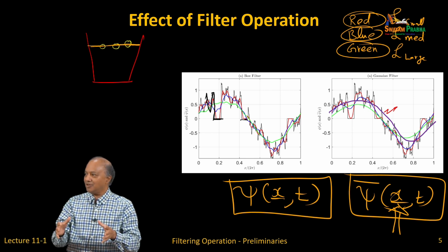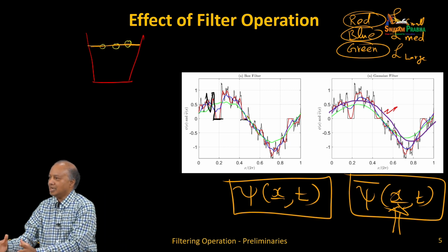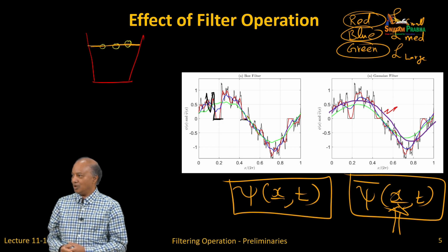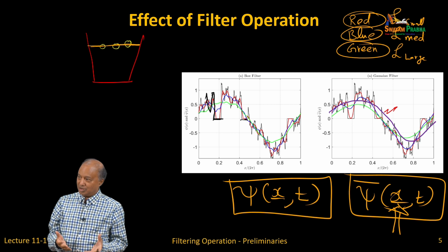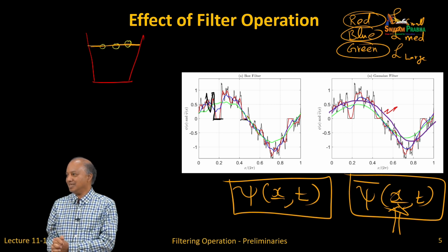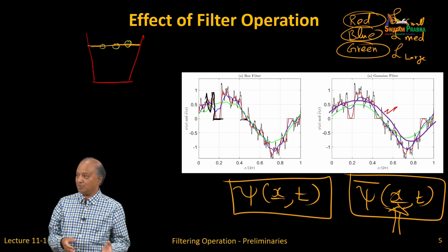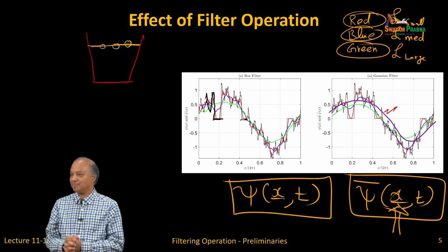So, you have transferred all the computational difficulty to modeling difficulty, right. So, RANS model is easy to compute, but will it give a good answer? Well, it depends on your models. When you do particle resolved simulation, it is hard to compute, but your answer you can trust. And LES is somewhere in between.